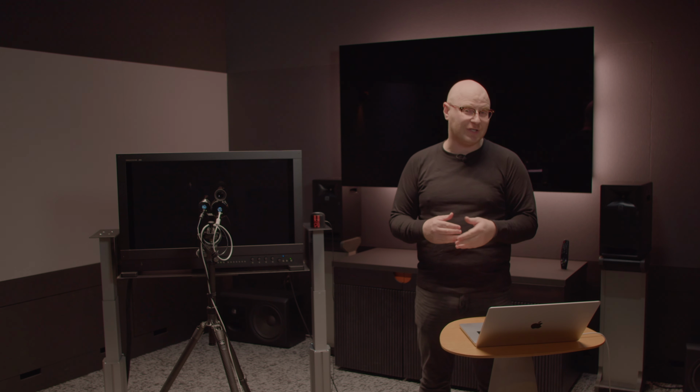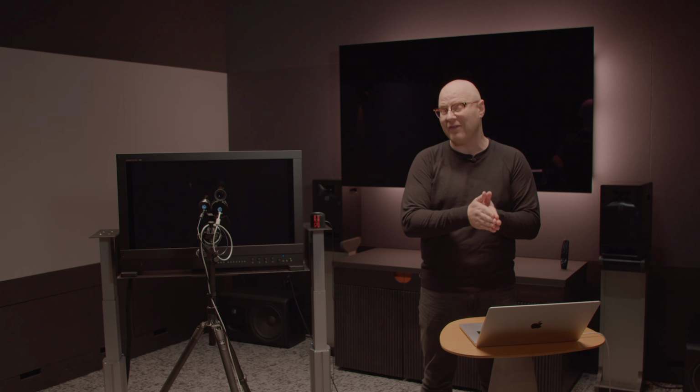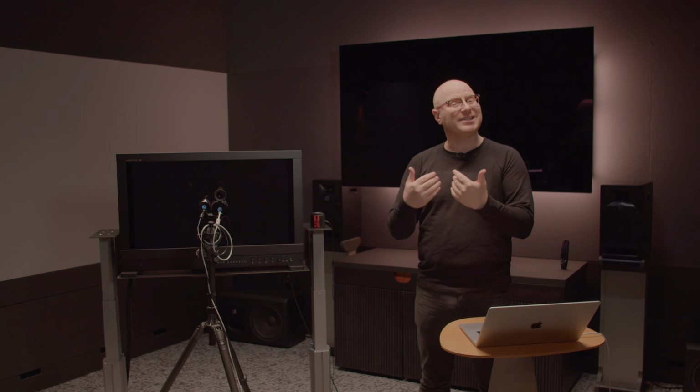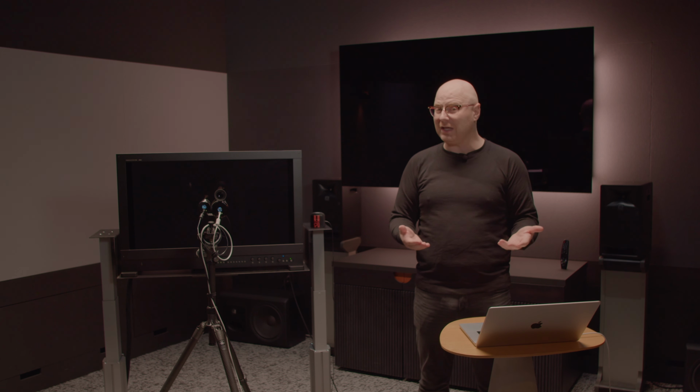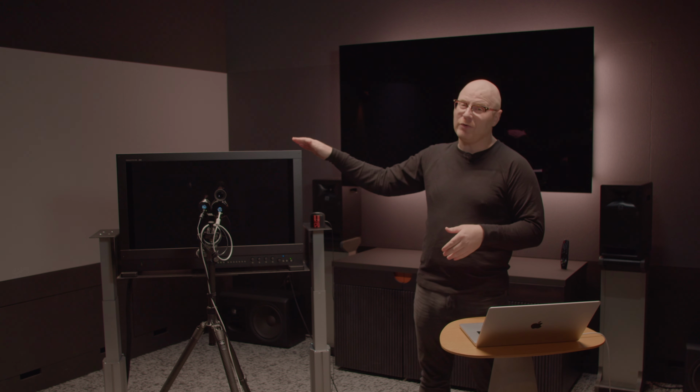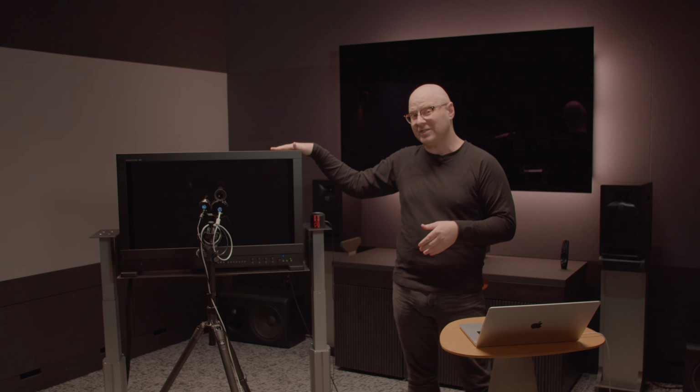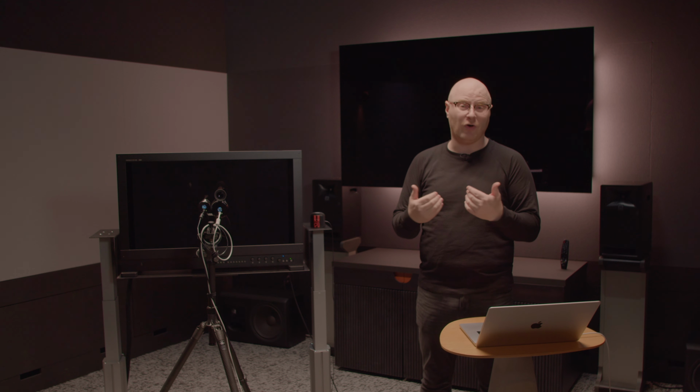But when CRTs were king, this is what was used on CRT after CRT, and they matched very well. Once RGB OLEDs were introduced into the market, they had a very different spectral power distribution, which led to metameric failure when looking at D65 calibrated using the 1931 color matching function. To combat this, Sony found that using the Judd modified color matching function and calibrating to D65 made an RGB OLED look similar to a CRT. This became sort of a standard practice, even though it wasn't a standard that we were all using to calibrate RGB OLEDs. As other technologies, such as the dual cell modulating layer LCD in the Sony BVM-HX310, came to market, we also noted slight shifts in those technologies, leading to the suggestion of alternative white points.